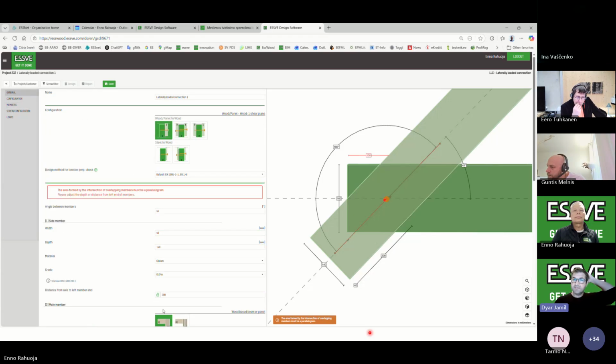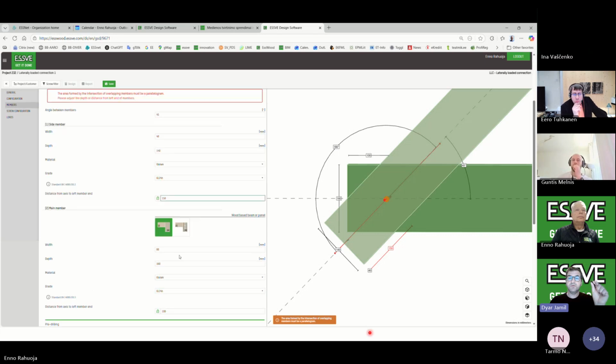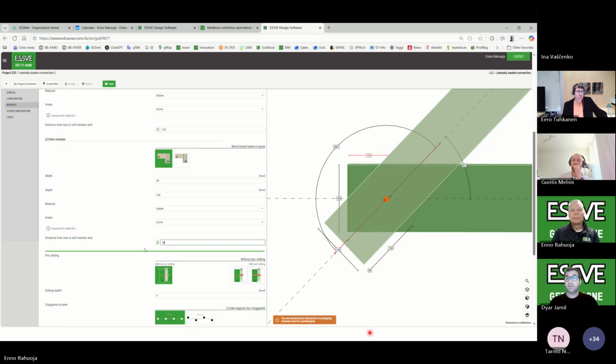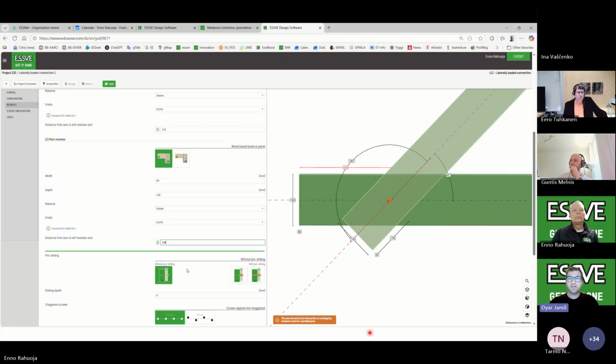But sometimes, as a structural engineer, you have not 100, you have 190. The contact area is missing almost 5 or 10 millimeters. You can use your engineering judgment as the solution. Say, okay, I will calculate it as 100% contact area, and for these 5 or 10 millimeters, it does not matter. That's what is meant by the overlapping member requirement being fulfilled. Yes. Like this.